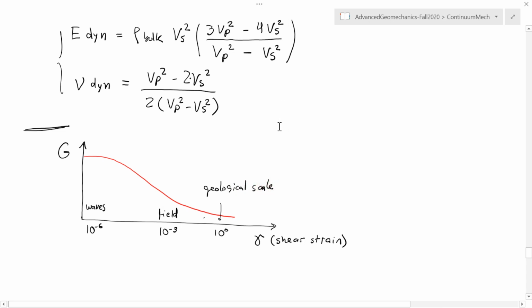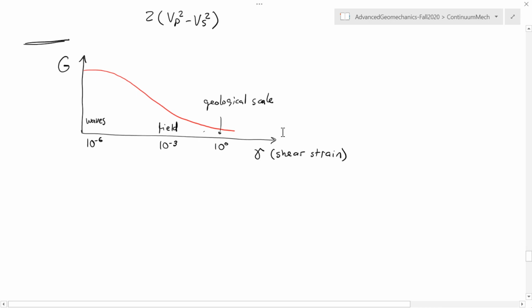And this stiffness of a rock is going to be also a function not only of a shear strain, but also of the shear strain rate. So I can do the same thing, plot the shear modulus. Now let me plot it as a function of 1 over the shear strain rate, where from here this means a derivative in time, so it's in a strain rate.